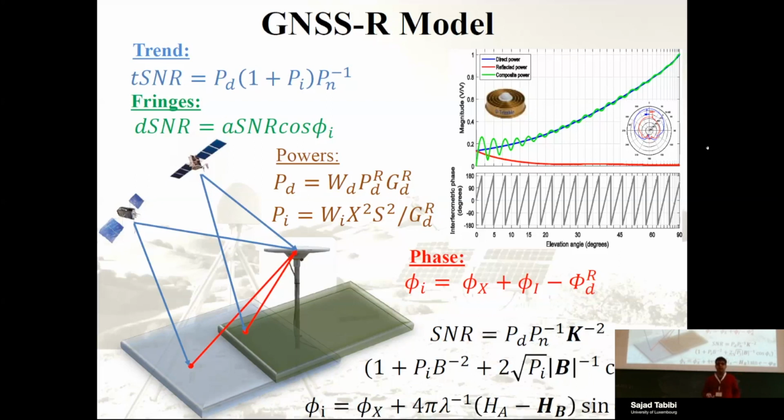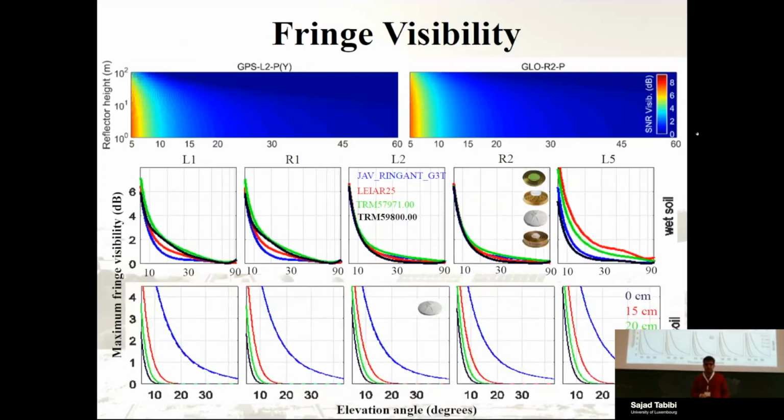So we develop a model here by including some terms. What we do is, we have a forward model where we simulate the surroundings of each GPS antenna using a least square spectral analysis, and then we use those values as a priori values in a weighted least square adjustment to find the corrections, using the variance covariance of different satellite tracks from different directions to improve our result.